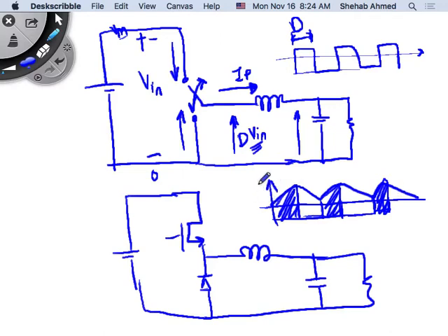So the average value of this up and down waveform was IL. The portion of it that I've shaded was the switch current. The width of that will depend on the duty ratio. So I will always have a switch current that is dependent on the duty ratio and the current here. You agree? Always, in all the circuits. It's the same, right? And we will use this conclusion to draw an equivalent circuit of all these power supplies without switches.